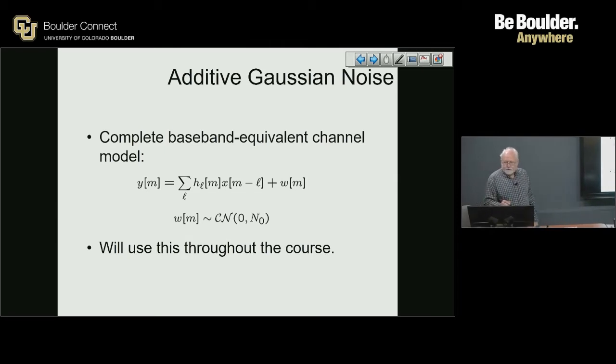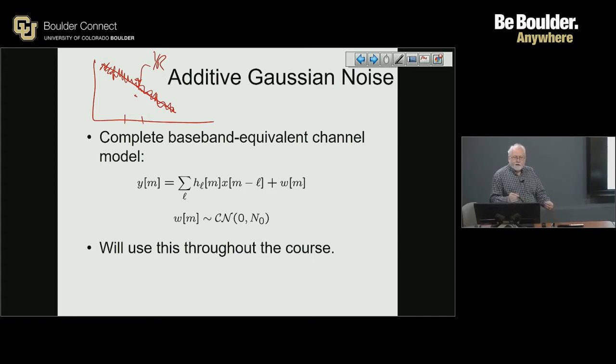There's another way to think of this, and that is if you look at the path loss. This is the way we typically draw path loss. If it's 1 over r squared, then the path loss would have a roll-off of 20 dB per decade, or 6 dB every time you double the distance. But in fact, if you go out and make measurements, this is not what you get. You're going to have some that are less and some that are more. Actual measurements show this as being a very noisy thing, and that's because of all the multipath reflections. Sometimes you're in a fade, sometimes you're not.